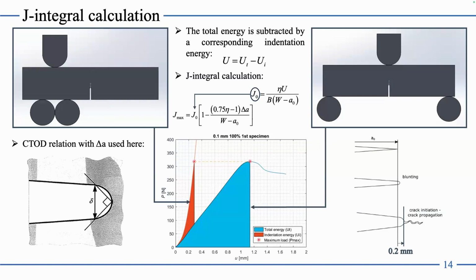So in our results from 100 to 50, we could interpret our results with K1C, but from 40 to 10, we had to use some different interpretations. For this conference paper, we'll show you just one simple parameter concerning the J max, so the maximum J integral value calculated from the total surface of the specimen.